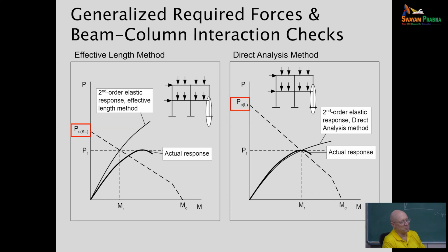So that's what we based it on. That makes for an easier discussion: our strength in the plastic hinge solution was tied very much to the cross-section strength at the top of that column. But in routine practice, we use KL equals L, and the reason is to cover the bases. If we have a very light column somewhere in the building that's failing in a non-sway mode, we want to make sure that we don't miss that.